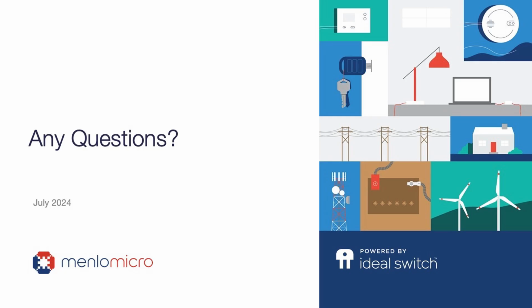All right, Tom, next one here in our queue. This one is asking, are MEMS switches vulnerable to hot switching? So yes, it's true that hot switching reduces the lifetime of MEMS switches. So for all of Menlo Micro's high-power RF switches, we guarantee 3 billion minimum switching cycles, cold cycling, with typicals around 50 to 75 billion.